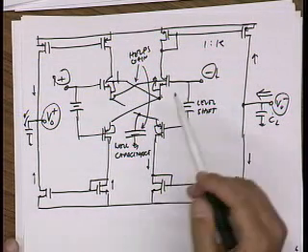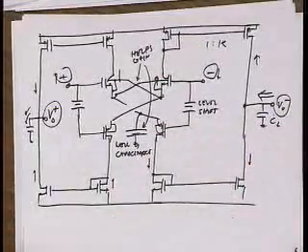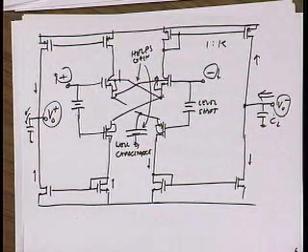It does require a lot of headroom, right? You've got lots of transistors in series here, a stack of 4 transistors. So give it a shot. It might be interesting to see what kind of headroom you can get out of this. But probably this won't work below 3 volts or so.